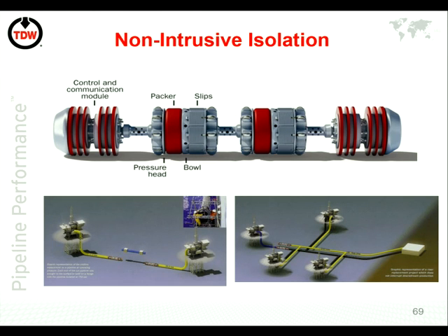You can't do this offshore. You're not allowed to leave fittings on pipelines. So that's why in most cases you don't tend to see hot tapping going on. So smart plug gives you the opportunity to isolate without leaving a fitting, and you can actually cut the pipeline either side. So this is all of the stuff that you saw with the stopple. This was done offshore Malaysia, and this was done using two smart plugs. And that's actually the pipe cut, and it was raised to the surface there, and then a new flange was welded on, and a new spool piece was put in there.